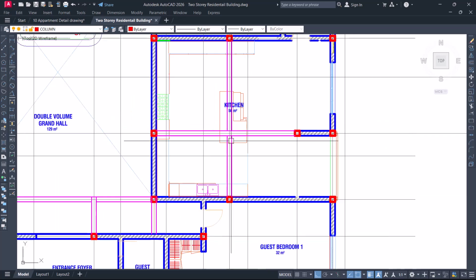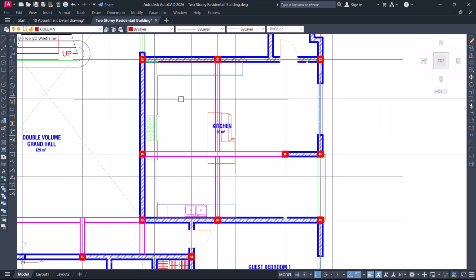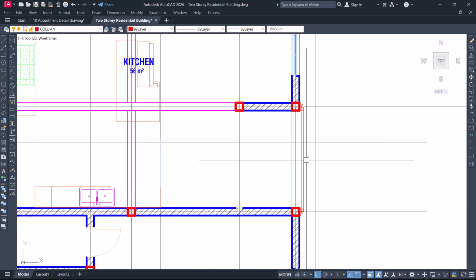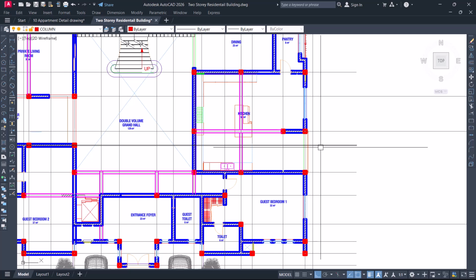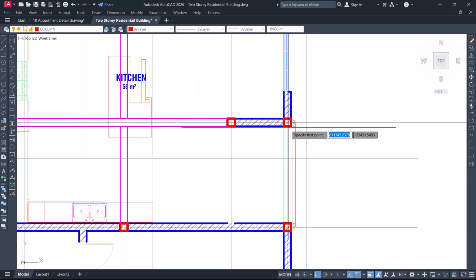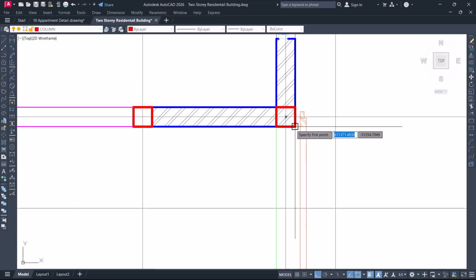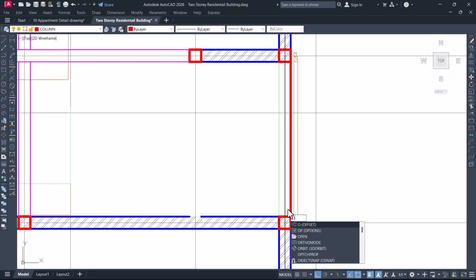So with that, you can see how I have broken this panel from being 56 square meters to having 4 strips of panels. Okay, that's fine. So there will be a beam running here for sure. So a beam will run here, that's fine. And again, let me see that a beam will run here. Let me just put a beam here. A beam will run here, but it will not have wall load because this is like a window all through. So a beam will run here, offset 225.